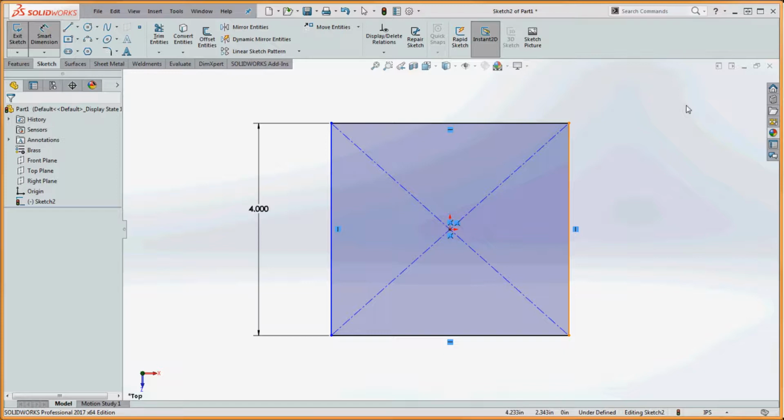And as I iterated in class, you need to have good sketch geometry in order to have a good robust model. If you have a lot of potential errors that might occur in your sketch, if you don't have it put together correctly, or if it's not really restrained, it has the ability to move around and change while you're doing modeling, and it could run into problems later. So you need to make sure you get all your sketch geometry down first, and then you can make modifications to it later if needed. So the way you do that is you have dimensions, you have sketch relations. So let's talk about dimensions first.